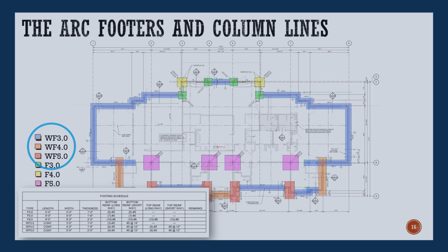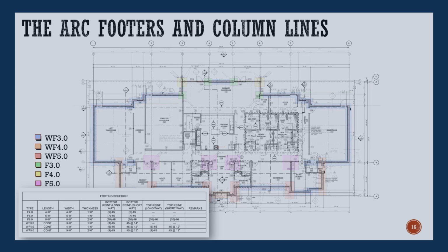Now locate the column lines that we will be using. Not only will these identify the columns, but they will be control points which we can measure off of. Always use both the foundation plan with the overall first floor plan when planning out your foundations. You will be surprised at the number of dimensional busts you will find when looking at these pages.